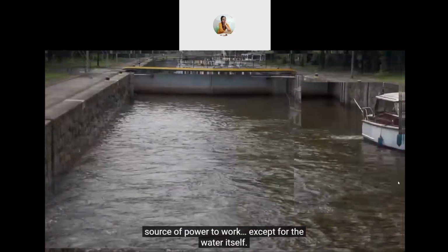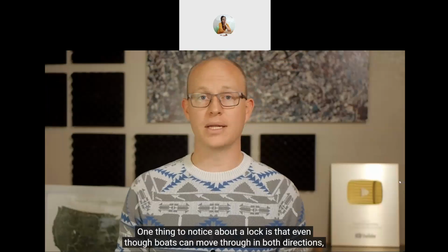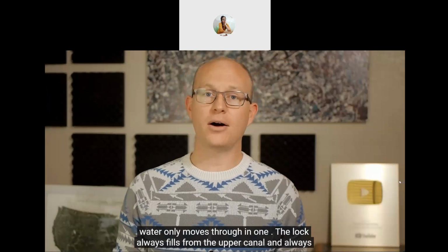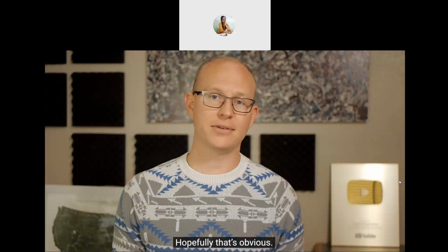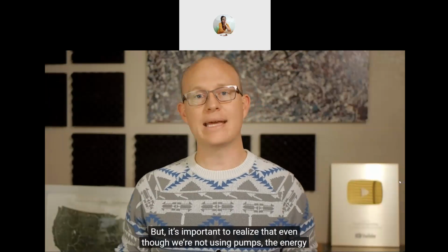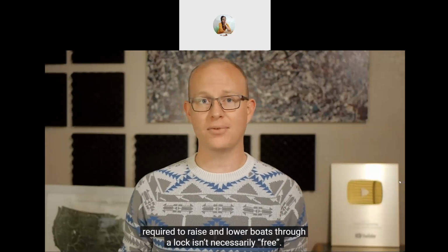One thing to notice about a lock is that even though boats can move through in both directions, water only moves through in one. The lock always fills from the upper canal and always drains to the lower canal. This is because of gravity, hopefully that's obvious, but it's important to realize that even though we're not using pumps, the energy required to raise and lower boats through a lock isn't necessarily free.